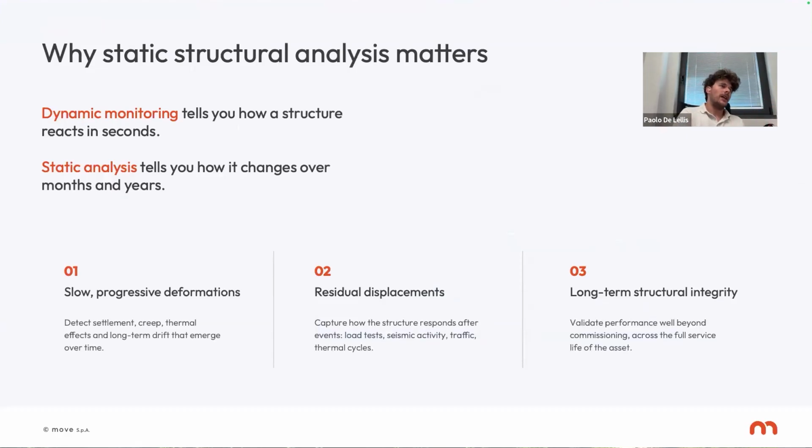One is dynamic parameters, the other is static parameters. Of course, with our sensors, you can monitor both, because I told you we have specific sensors like the accelerometer, the vibrometer, and the dynamic displacement sensor that allow you to monitor the vibration and the response of the structure to this type of vibration.